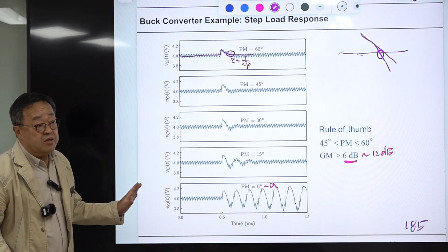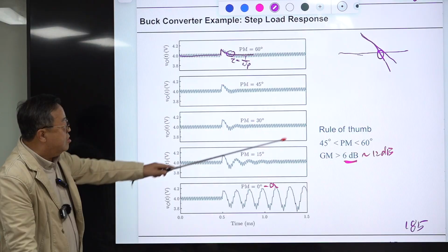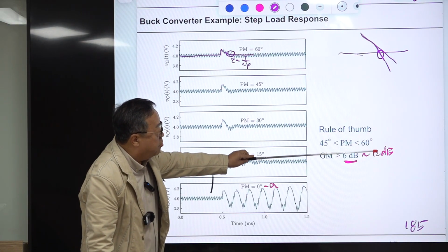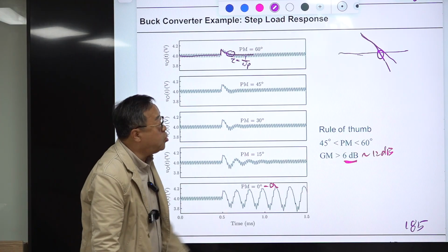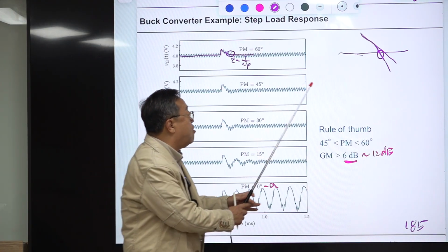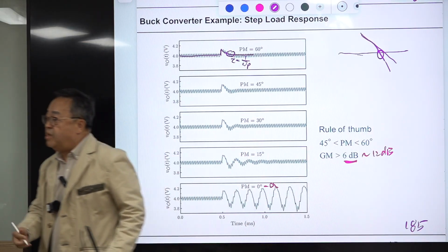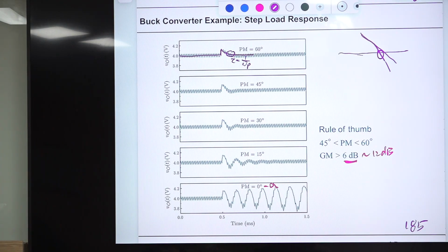does not mean much. Okay, so to have safe and robust stability margins, the crossover frequency should not occur where this slope is fast. Usually a -1 slope is desirable. Okay, a -2 slope is very dangerous.